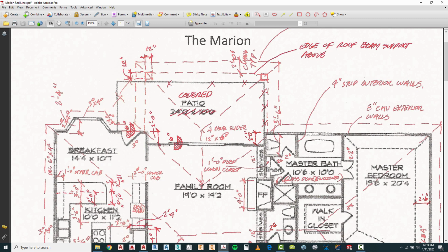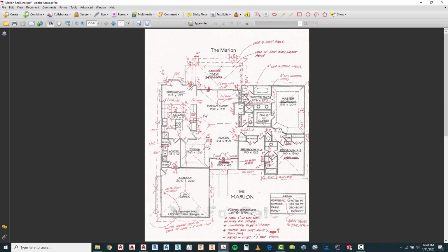And you notice the door is in here. I've located as 2 2-0 doors, which means it's a total of 4 feet wide. But you need a return on each side between this edge and where the door is in order to put your casings. Now I have added a note down at the bottom which says leave 3 inches on both sides of doors for casings. So using that parameter, we're going to establish where our door is located with 3 inches here, another 3 inches where the front of our countertop is, and knowing that the countertops are 2 feet deep, we'll be able to set up our wall right here.